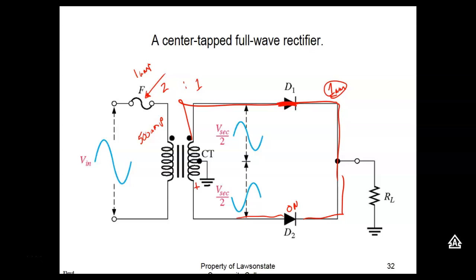Now, roughly, I'll try to give you all the actual NEC ratings on transformers. Normally, we understand that in power supplies, we have a lot of surges and everything when you first turn power on. So the power supply has to let these surges go through. So it's usually at least 150% bigger over there.